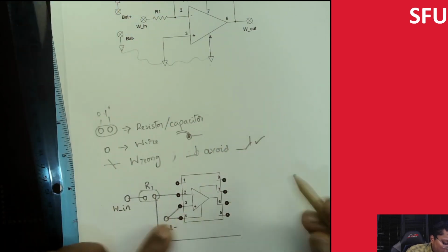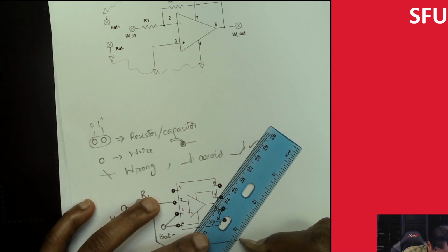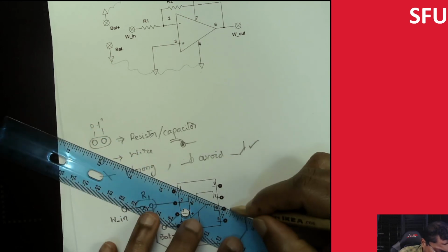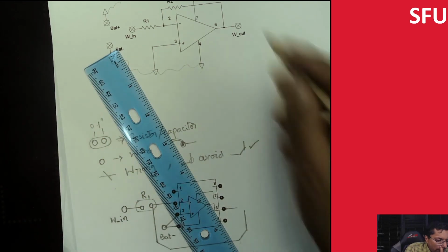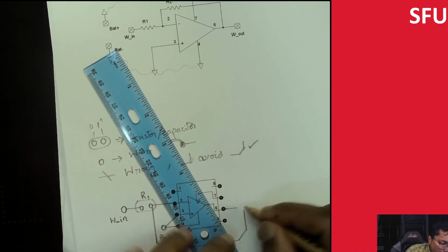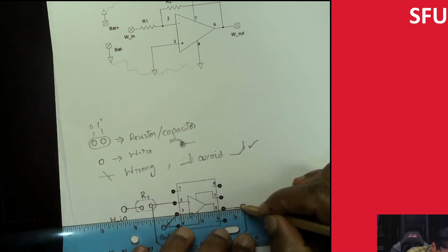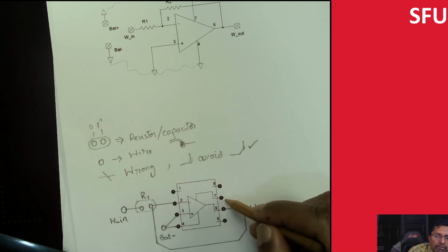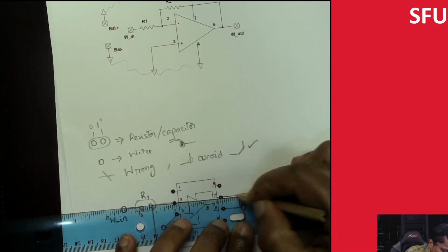You notice that it might actually be easier to connect it like this. So I'm going to put my wire. Since I need to get a W out here, I can either do a 45 degree and make it more complicated, or I can simply connect both of them at the wire out. So maybe just wire out here, connect the 6 over here, one here, and just label this W out. Let's go to here. Pin number 7 needs to be connected to battery in, so let's send this out and then put a wire connection here.